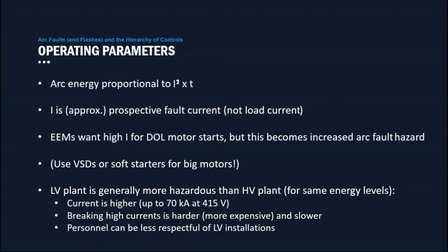Now, most electrical engineering managers in the mining area, in particular, want very high fault currents for direct online starting their big motors. So on the plus side, you can DOL a large motor, but of course on the other side, your prospective fault current is very high, and if you do have an arc fault, then you've got an even bigger problem.